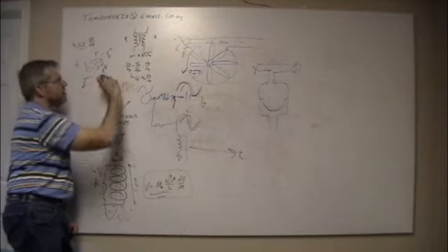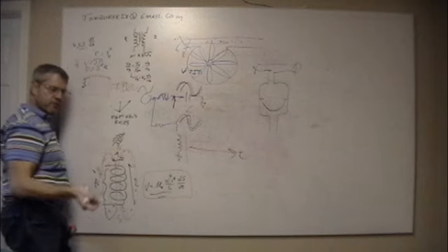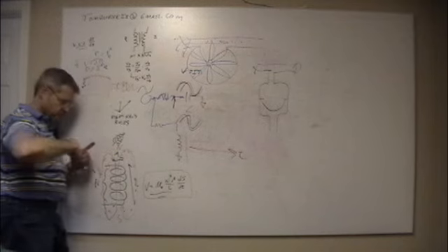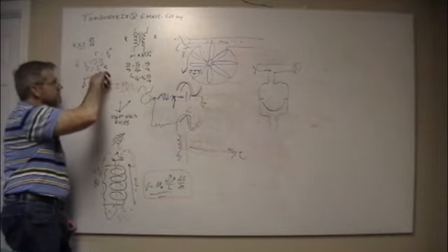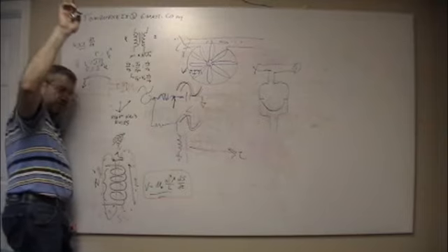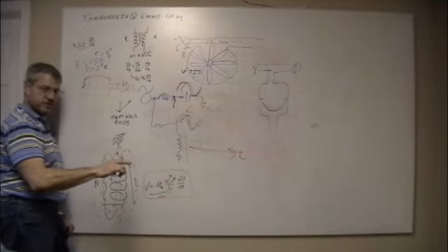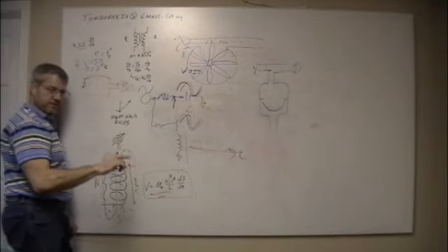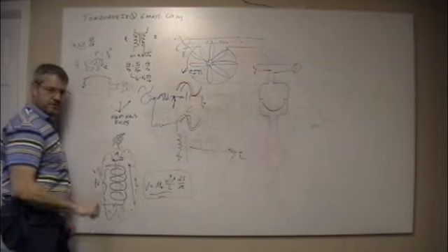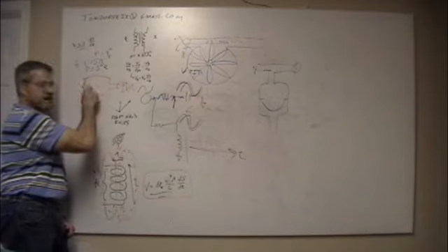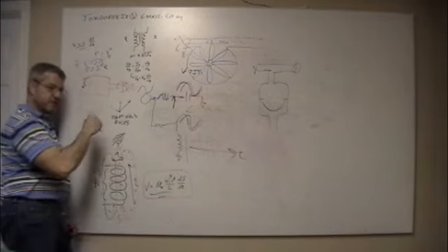But then when I come off, and this thing's coming out of the page, and I'm off of where I would be generating my peak voltage, which is where I'm perfectly perpendicular to the magnet, then my current's shooting through the roof, because to maintain the V over R, the P equals IV relationship, if V's going down but power's remaining the same, I has to shoot through the roof, which is causing this guy to overheat when he shouldn't be. He's causing him to heat when he shouldn't heat.